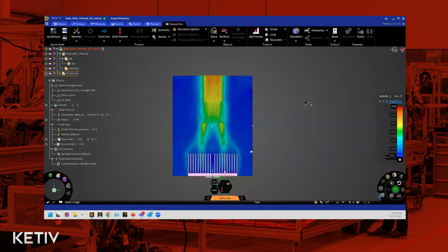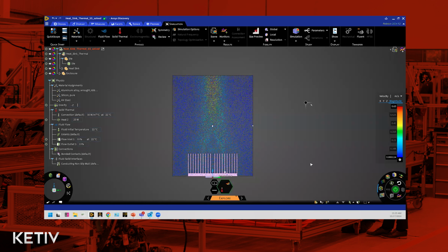So you can see a little bit of those convection currents that we discussed early on in this particular problem, right? And you can look at particles as well, depicting the path line of the flow as it moves through the heatsink domain. The important thing is to make sure that you're resolving the space correctly so that when the flow is being computed, it's taking into account these thin clearances and producing the results accordingly. Okay, so I'll wait to see if anybody has any questions.